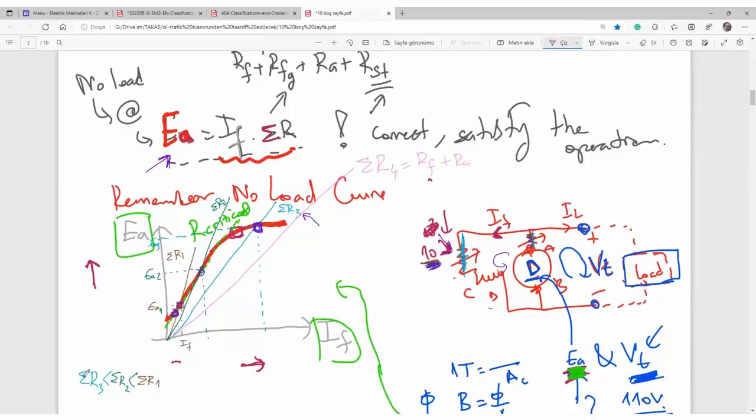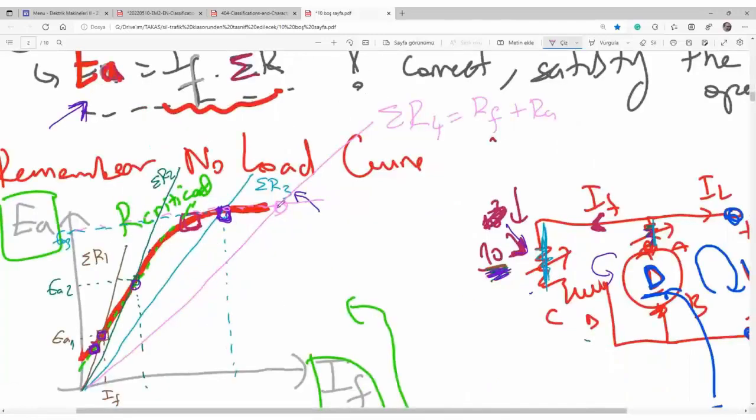There is no additional one. In such a case, here you see the possible operating voltage is close to the previous one, because the machine is saturated. There is no more increase in the EMF due to saturation, because here's a straight line, but here's a saturation curved line.